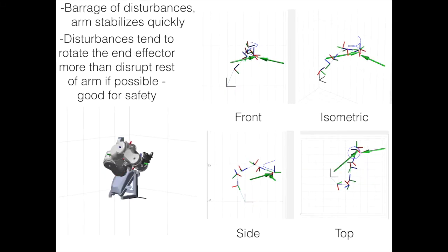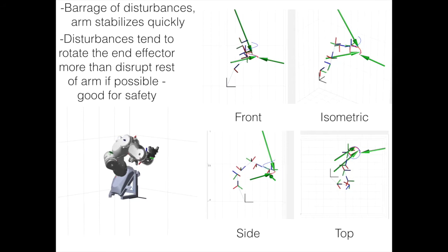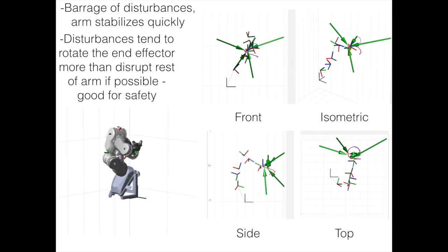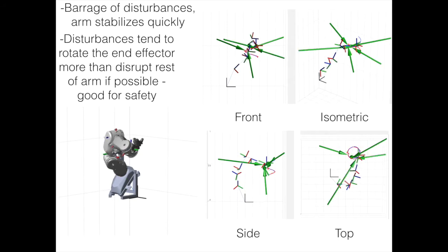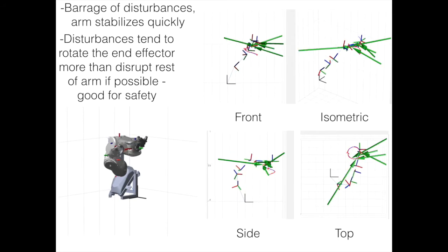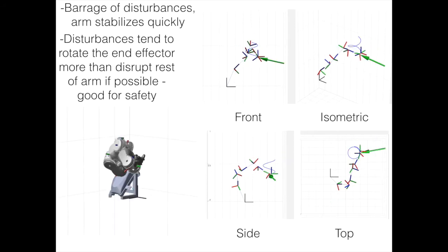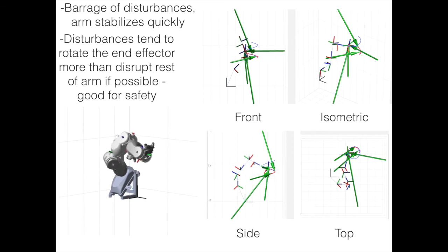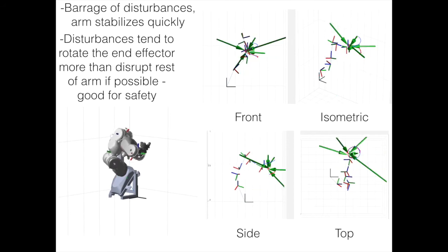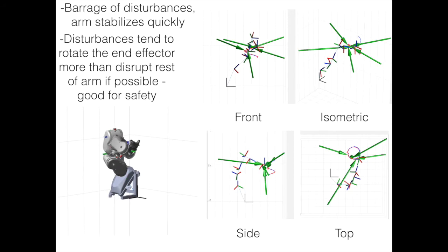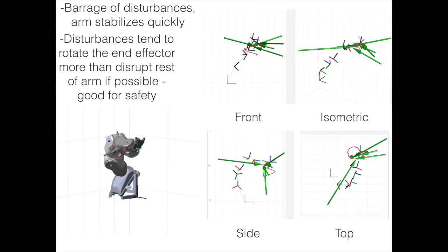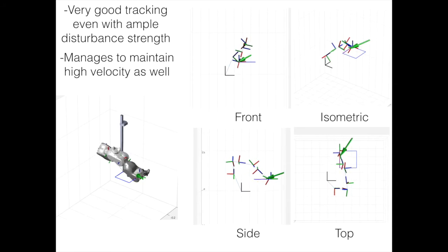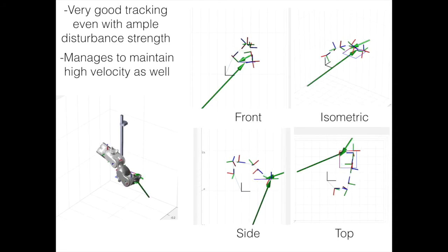After we confirmed that we could follow our chosen trajectories closely, we added in disturbance generation. We hypothesized that using a lower constrained finite time optimal control horizon would be very detrimental for disturbance rejection, and our results were generally consistent with that hypothesis. We found that for n equals 4 compared to lower values like n equals 2, even when multiple forces were applied within a short time period, the arm was able to stabilize itself and stay on the trajectory. Furthermore, it was able to generally reach the end of the trajectory only slightly slower, because the controller weighted distance from the trajectory points more heavily than preservation of velocity.